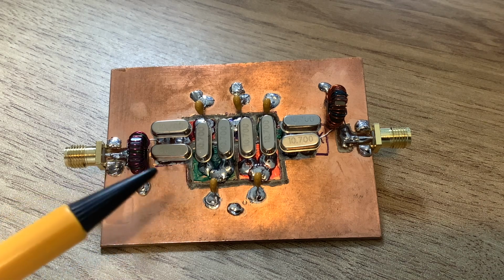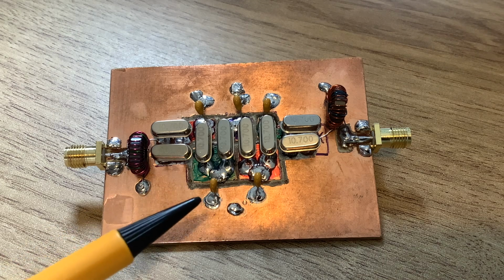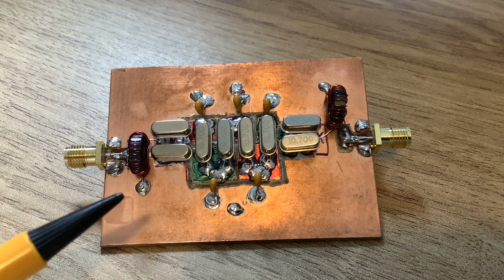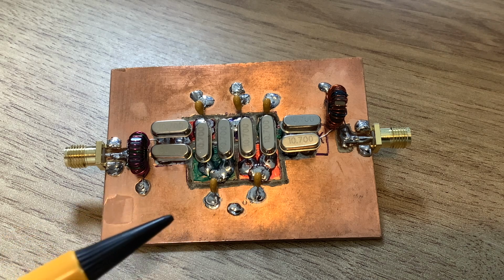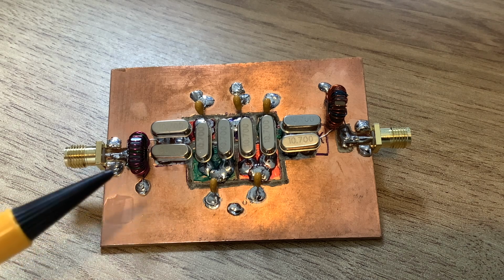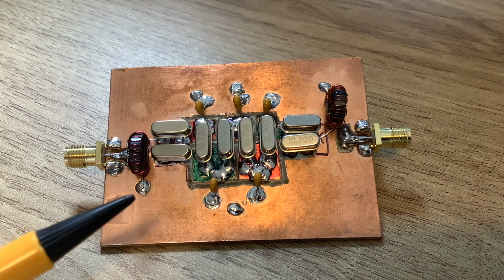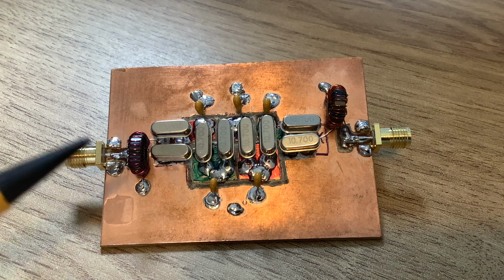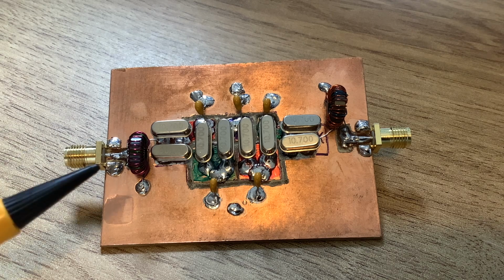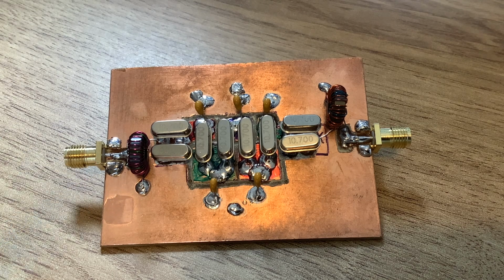So as you increase in bandwidth, you decrease the capacitance, but also you increase the input impedance. So if you've got a much narrower filter, you'll find the input impedance is much lower. And that can be useful if you're building a sideband filter, or certainly if you're building a CW filter, much more forgiving. I've got 1,200. I've got to match it to 50 ohms. So I'm not going to go into all the details of this now. I will just give you the figures.